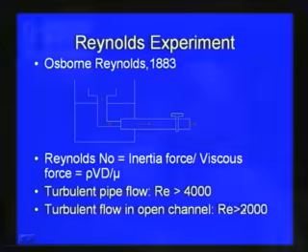600 something, the flow is laminar for channel flow, and from 600 to 2000 it is the transition stage, and then beyond 2000 the flow in open channel flow becomes turbulent. So, with respect to the Reynolds number, we have already seen how we classify the flow as laminar and turbulent.